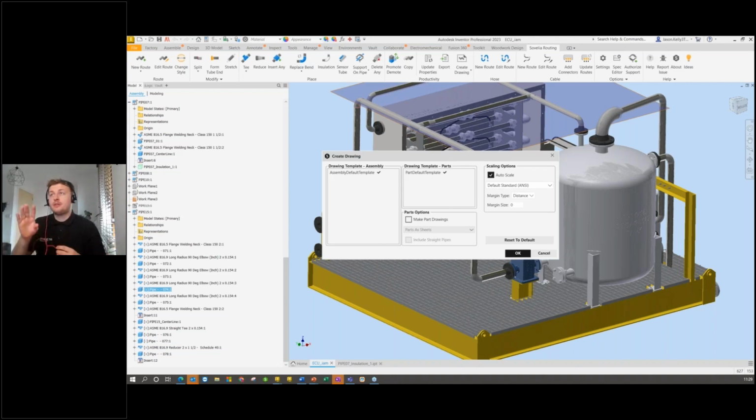Yeah, so it's a good question. The insert any function is more for inserting any fitting or fixture. So that's not about inserting other models. But what's different about the Tube & Pipe environment is you need to publish the component and link it out from that particular component. And that's probably where you were seeing some of the issues when importing third-party models, because the Tube & Pipe environment is designed to be quite user friendly. It's picking up on the circular reference, so you wouldn't need any configuration with your third-party models. You just import them using the Inventor any CAD functionality, and then you just pick up on that particular reference geometry that's within there.